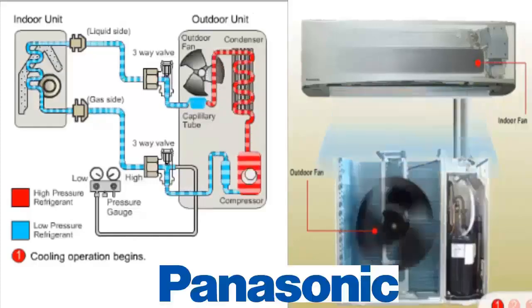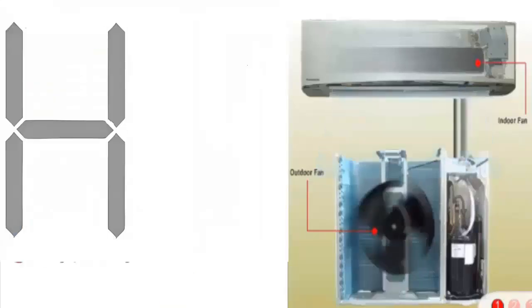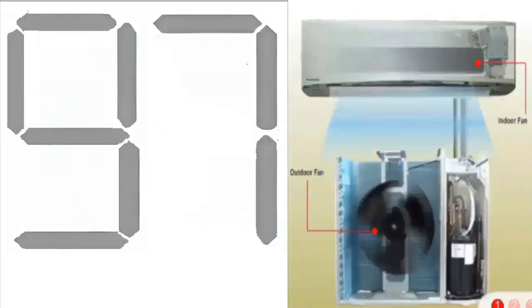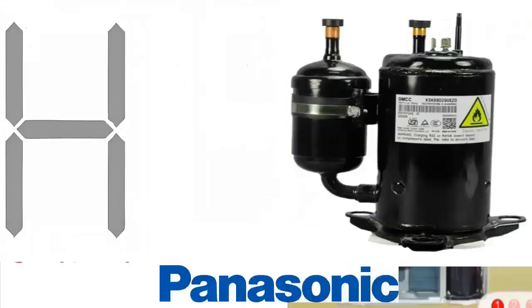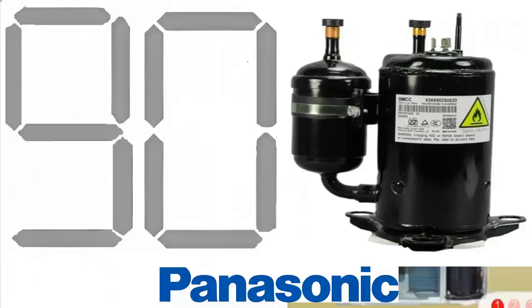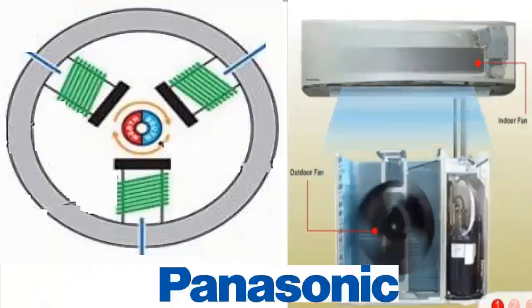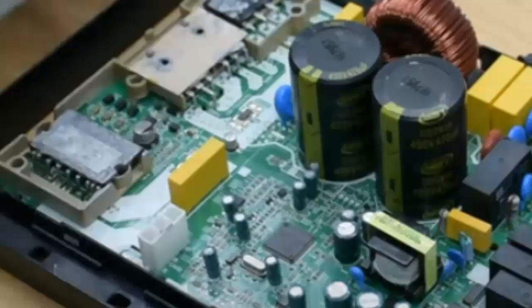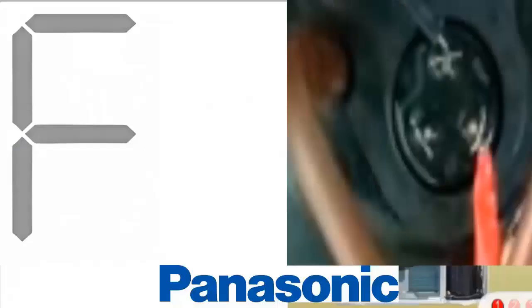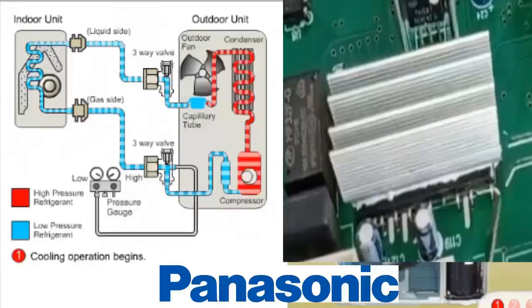The following codes have similar diagnostic procedures. Error code H97, related to a defective compressor motor. Error code F90 indicates an open circuit in the compressor windings, a difference in winding resistance, or a fault in the inverter board. Error code F93 refers to open compressor windings or malfunction of the inverter board.